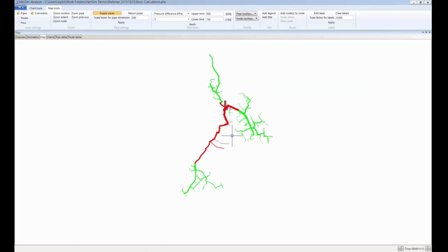And also we would see if the pump would affect, you can now see that we have very high pressures here that we didn't have before. So that's something to evaluate. Is that a problem for us, that the pressure is now higher here? And it's something that NetSim can show us. Where is the pressure now high? And are there any problems associated with putting this pump to ensure we get a high enough differential pressure down here?